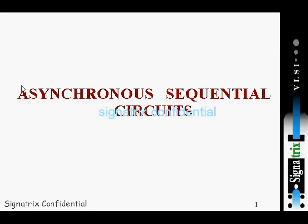So the topic of today's discussion is asynchronous sequential circuit. Asynchronous means sequential circuit, we know that circuits work with respect to a clock. So how can you say that a circuit is asynchronous? With respect to what are we saying it? Suppose two domains are there. If one domain is working at 40 megahertz and another domain is working at 30 megahertz, then for the 30 megahertz domain, the domain working at 40 megahertz is asynchronous. So we should speak in terms of asynchronous with respect to what we are saying.